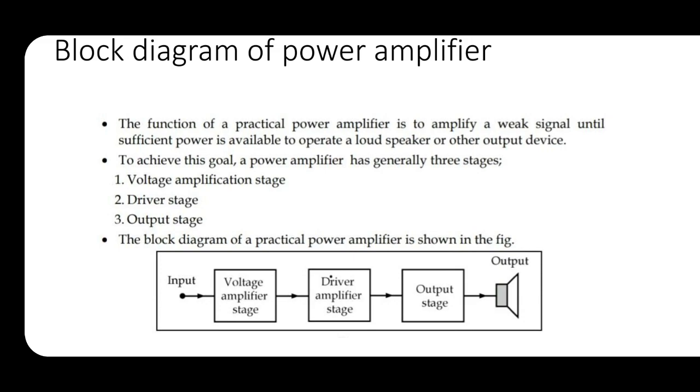The voltage amplification stage cannot drive the output stage alone. The purpose of the driver stage is to produce enough current gain in order to drive the output stage. Since there is sufficient current gain, the driver stage produces a considerable amount of power gain too. The driver stage provides power amplification as well. So the driver is connected in between the two stages.